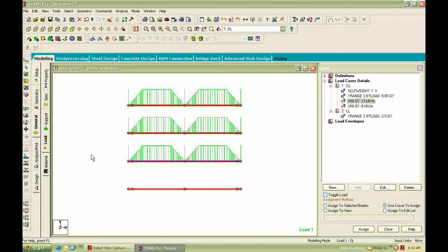Now there is again a mistake. I don't want this top floor. Actually the wall load 2.5 meter height walls will be coming for between ground to first and first to second and first to third. Above the third floor it won't be 2.5 meter. It will be a parapet wall. Parapet wall generally will be of height 1.2 meter. So this roof should not come into picture here.